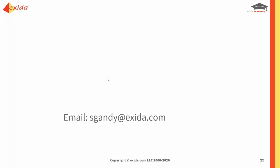Does the life cycle methods vary in methods or rigor with the level of SIL that is to be met? Well, the requirements are laid out for the rigor on SIL. The process is the same. So if we've got a SIL 1 or a SIL 3, we still have to go through and do the equipment selection. And here again with SIL 3, the standard gives some guidance.